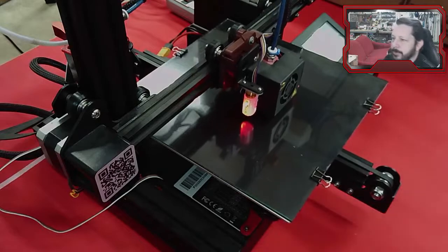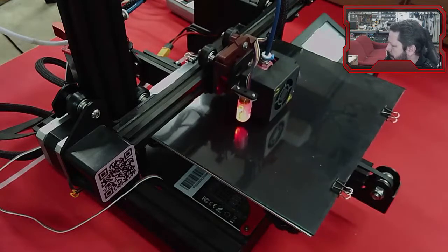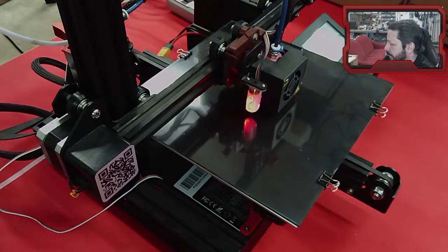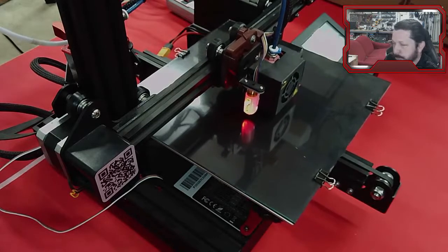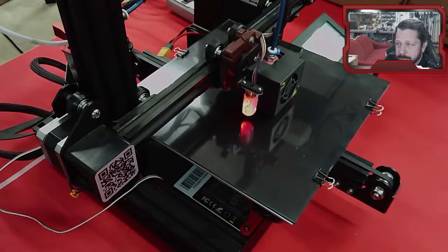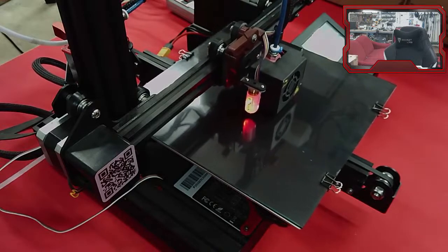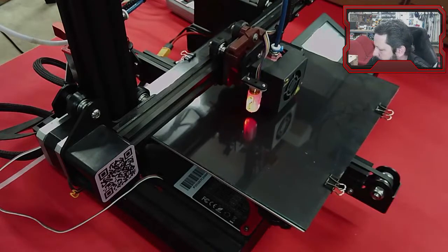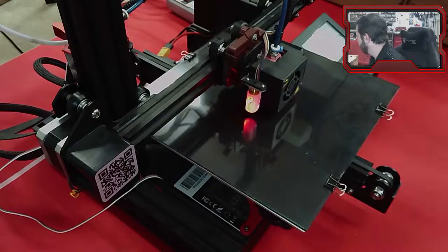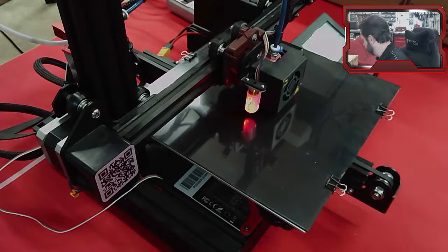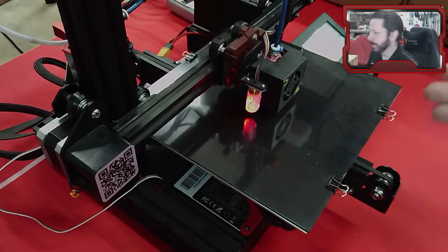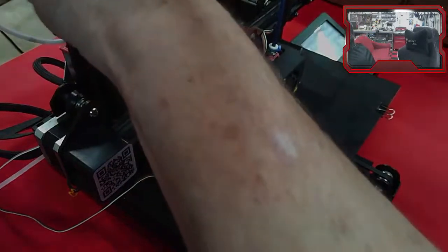And what you want to look for, you can't see it because it's underneath this thing, but what you want to look for is that it is squished down to the glass, but not so much that it's barely extruding any plastic. This one looks pretty perfect, so I'm going to let it go. I'm actually going to move it out of the way, and let's start looking at our... It said it was only going to take 9 minutes, so let's just move it back.